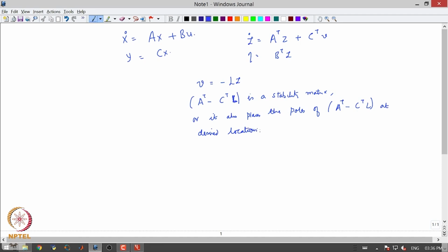Now, when is this possible? This turns out to be a standard pole placement problem for linear systems, which we saw earlier. So what was the necessary and sufficient condition for pole placement of x dot is Ax plus Bu with u equal to minus Kx? Well, that the pair AB is either controllable or the weaker version, stabilizable.